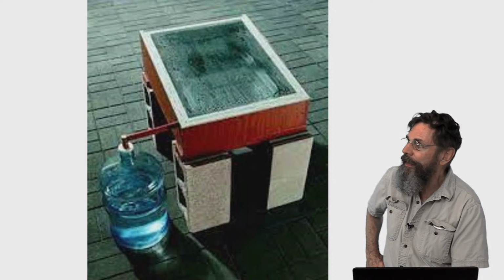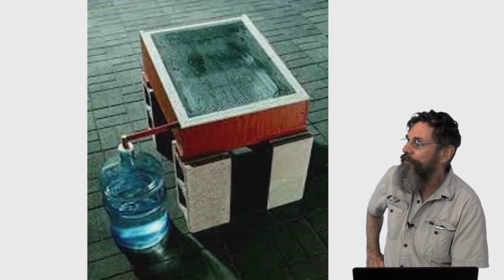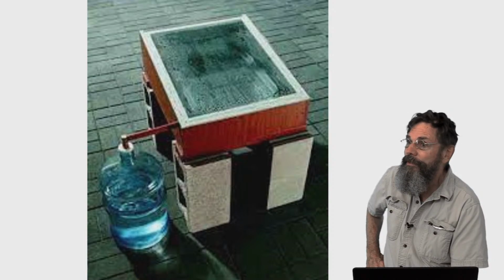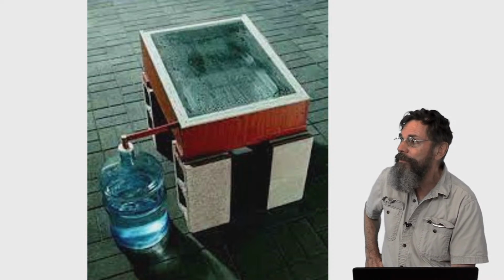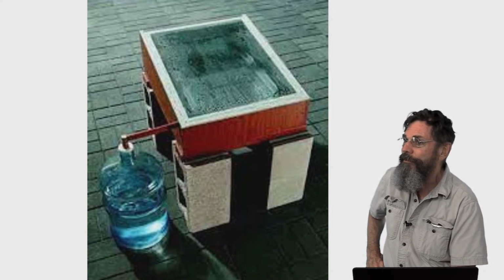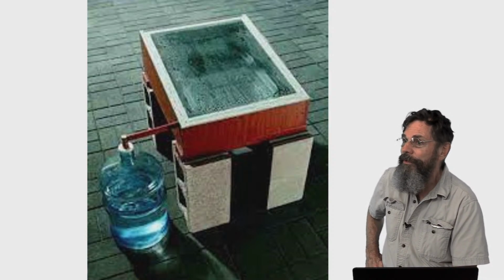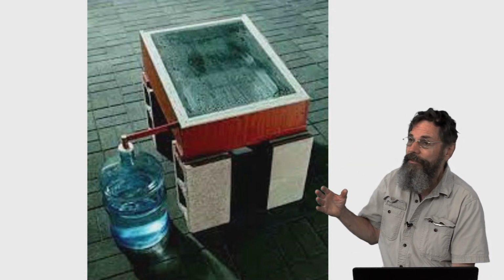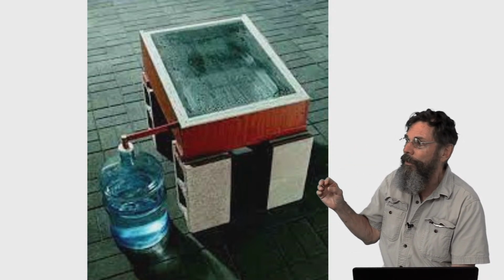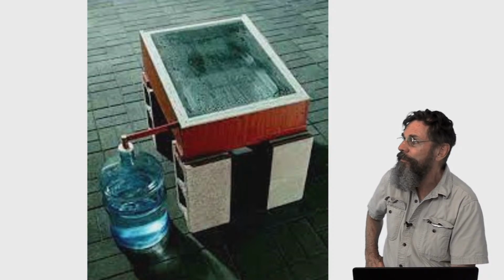And again, something that small, you can get away with using just regular cut sheet glass. Ideally, when you get bigger designs, you would want tempered glass, which can get into some money, because tempered glass is much tougher, and when it breaks, it doesn't slice you. If you fell on it, tempered glass may not shatter, but if it did, it would break into very small pieces. It would be much less likely to injure or cut you. Plate glass will break into shards and could hurt.